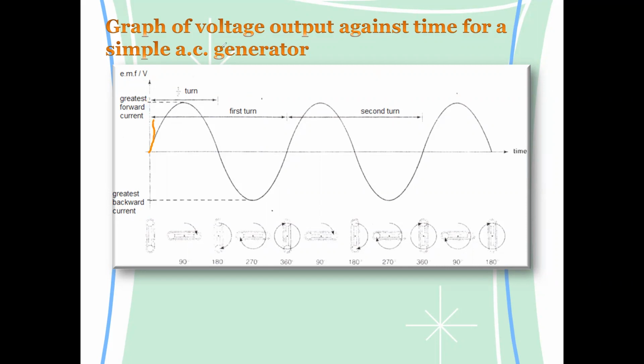So due to greater change in the magnetic field, there is higher induced EMF, but the number of cycles in the same duration will increase as well. Because if I'm moving it faster, in a short time the coil can complete its rotation. So the sketch will vary depending on what change we do. If we move it faster, there will be a greater change, and in a short time, it will complete a cycle. If we only change the strength of a magnet, there will be higher induced EMF, but the time to complete one vibration will be same.